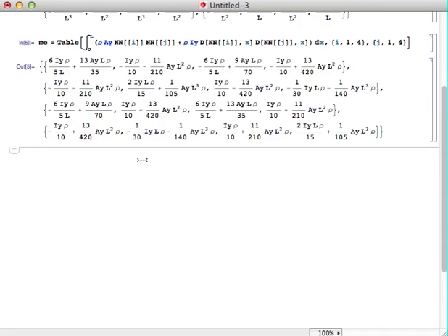All right. So we still have to apply the boundary conditions. Now we just have one element here. If we had multiple elements, we would do an assembly procedure just like we had before, except now we would assemble the mass matrix, and it'd be exactly the same as the stiffness matrix because they're the same size, right? So we'd assemble the mass matrix and assemble the stiffness matrix, and then we apply the boundary conditions. Here we only have one element. It's a cantilever beam, so at node 1, both the transverse deflection and the rotation will be 0.